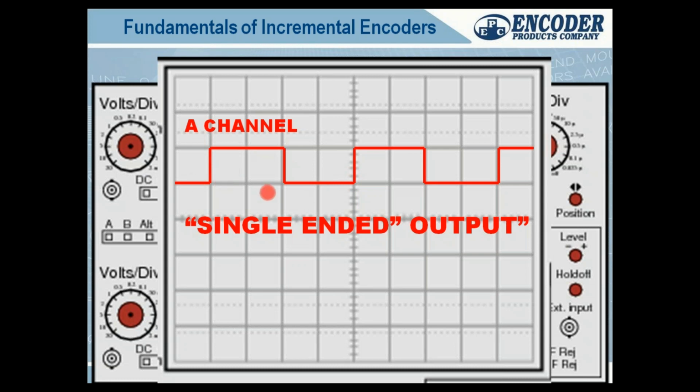Now, when you get those, what can you do with them? Well, you can count them, right? They're flying by because you're spinning the encoder on something, and you can count them and divide by time. Now you have a velocity, or you can get position. You can say, well, I've seen 500 pulses. I know my encoder's gone half of a revolution, and that means I've gone this far.